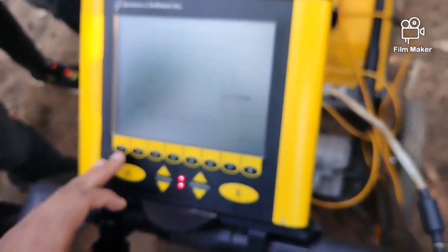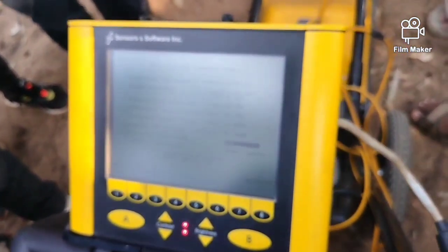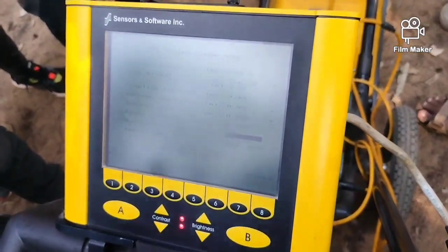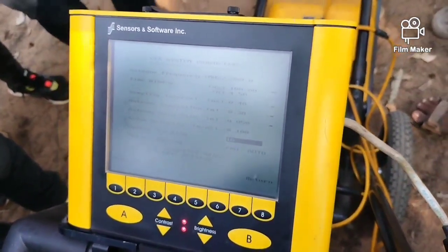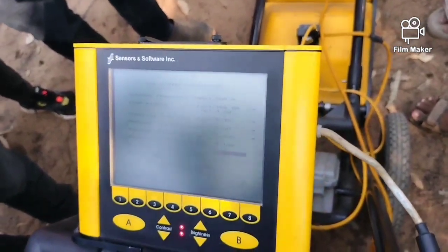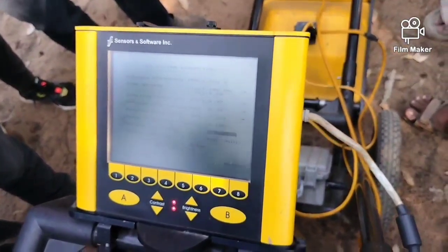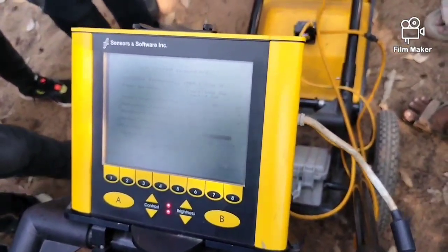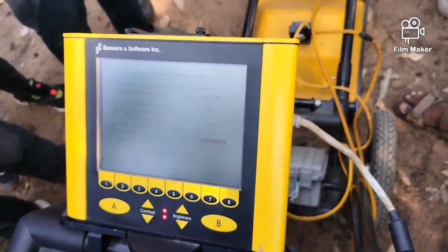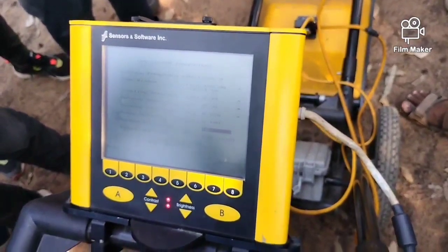Okay, system stacking is something... can anyone tell me what system stacking is? What is stacking, if you guys know? It is how many times the GPR would stack the same data at each point, because once you stack the same data, the error decreases, right? Because the average would converge to the mean. So the higher the stacking, the higher resolution or more accurate data we will have.